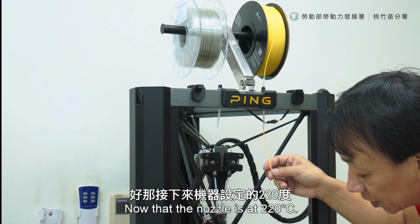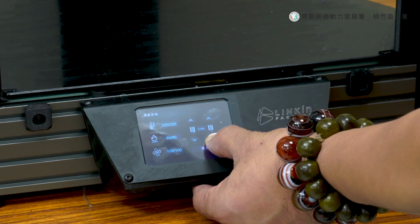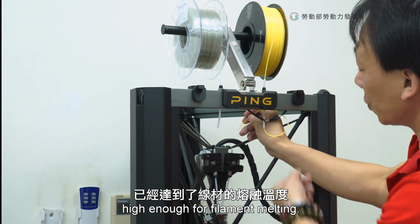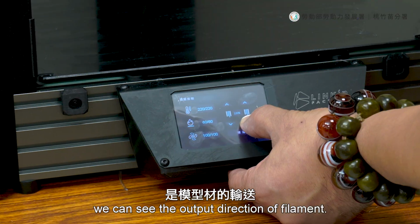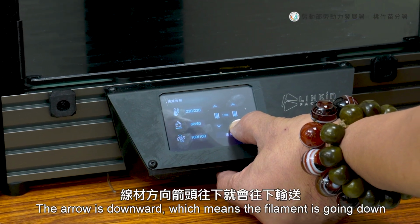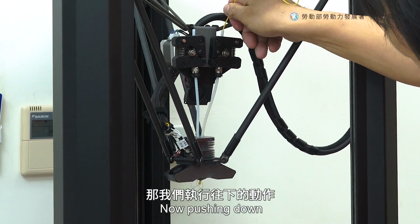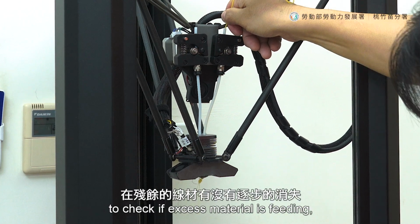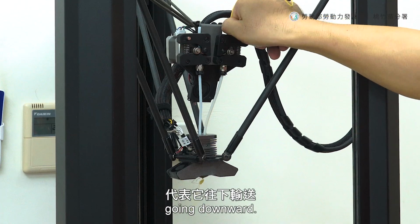Now that the nozzle is at 220 degrees Celsius, we can see it is at a temperature high enough for the filament to melt. Now on the right side of the panel, we can see the output direction of the filament. The arrow is downward, which means the filament is going down. Now push down while you observe the second duct in the nozzle to check if the excess material is feeding, going down.